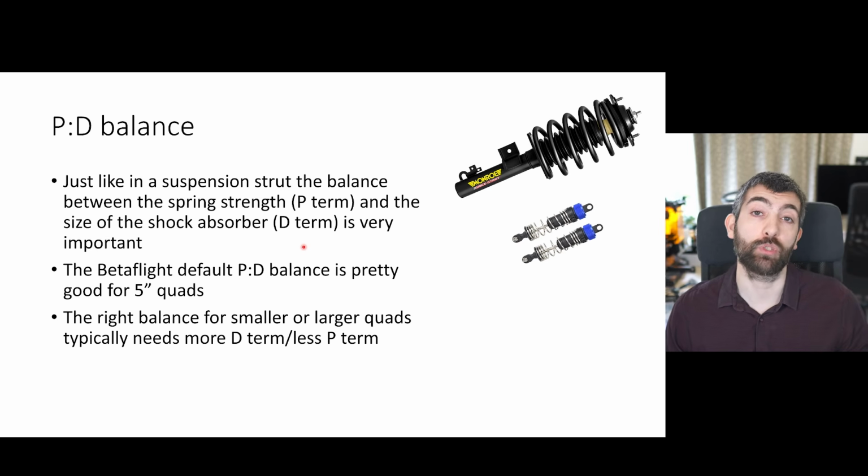But the ratio between those terms is what's important, not their absolute size. So if you double both the P and the D term, they will both have the same relationship with each other and you'll get a similar response.